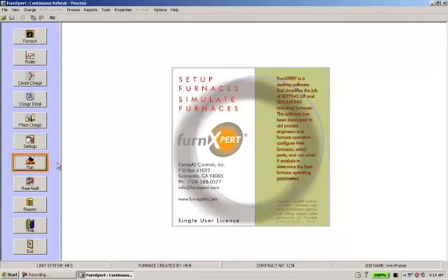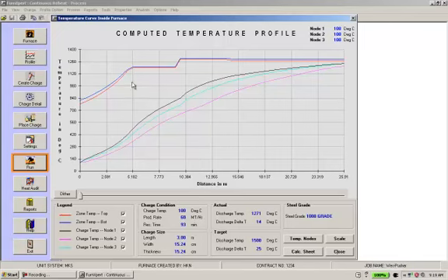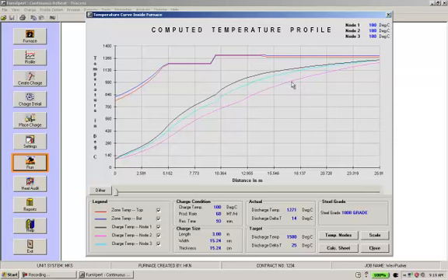Once you click the run button, you'll notice that this is the actual run that has been run in the background. The top lines, the blue and the red lines, are the furnace profile. This is pretty much what has been created, but in the unfired zone, the software calculates the profile and also calculates the flue gas temperature. The black, the sky blue, and the pink lines give you the profile of the top, center, and bottom of the billet that has been run.